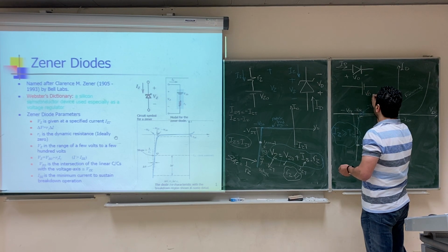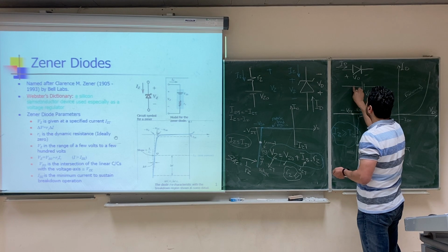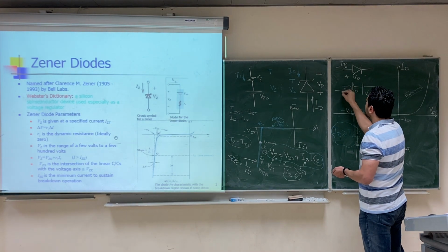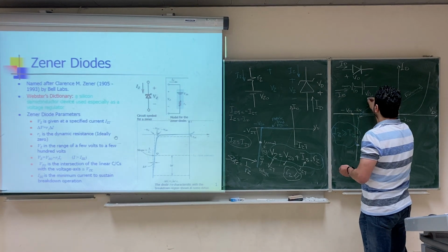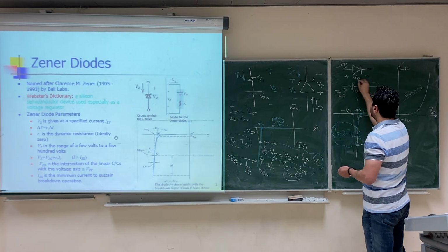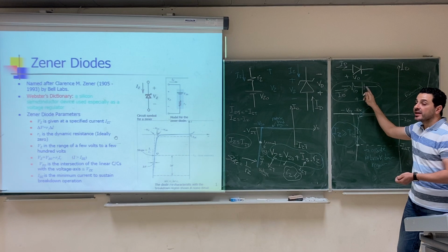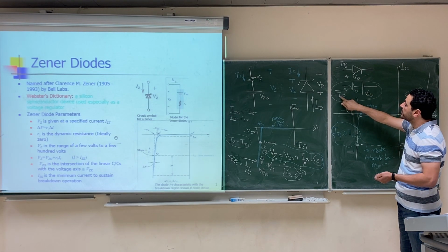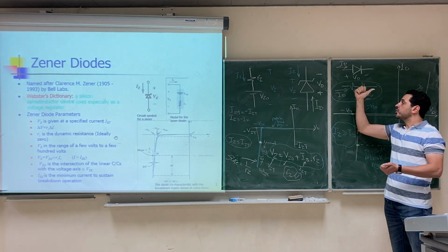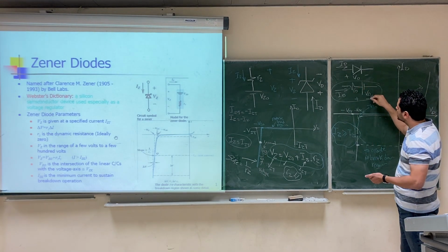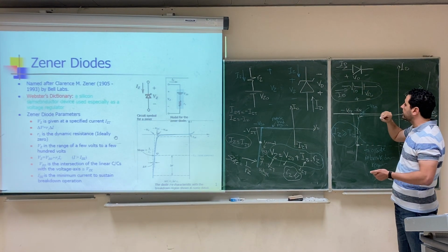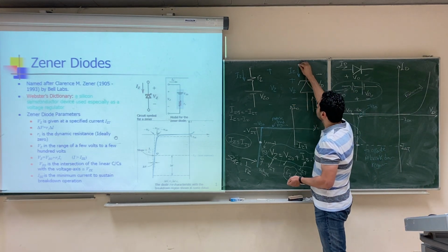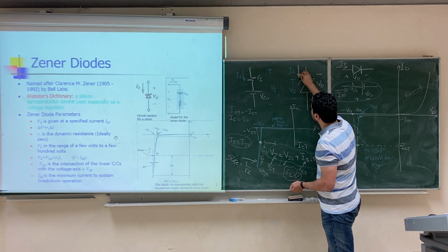So this is VDO, and we used to put maybe a resistance here, RD. The current was going in this direction, and VDO was in this direction. So in the forward bias, the direction of the battery is opposite to I diode. Because in the forward bias, I diode flows in this direction, the direction of the battery is negative here, positive here. While here, in the breakdown, the current flows in this direction.